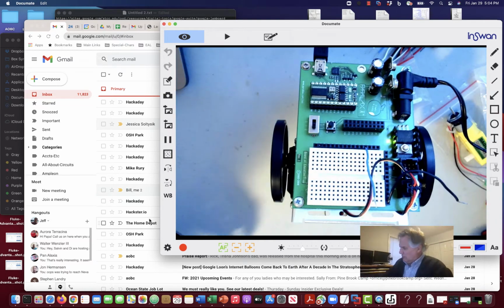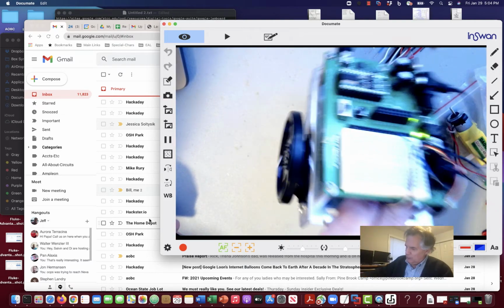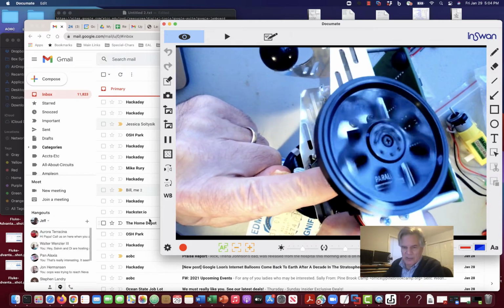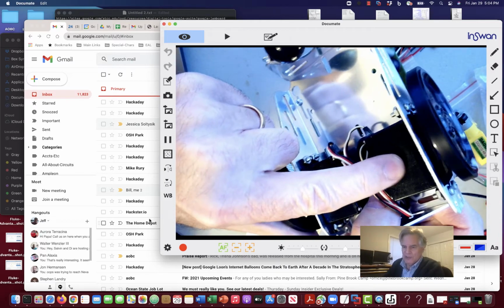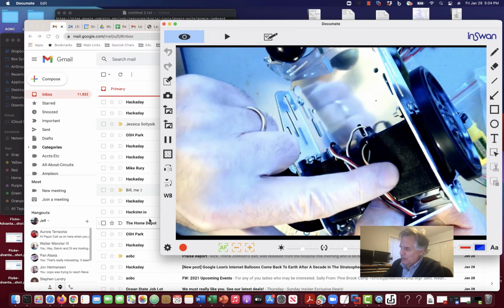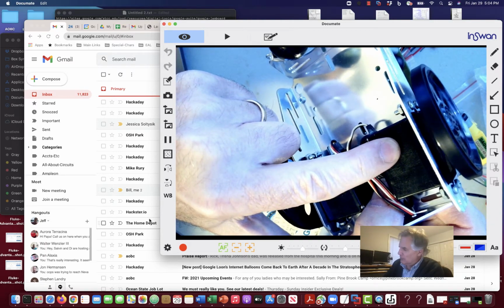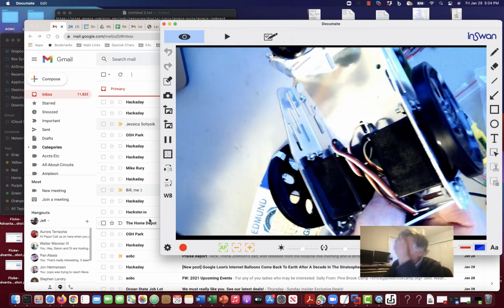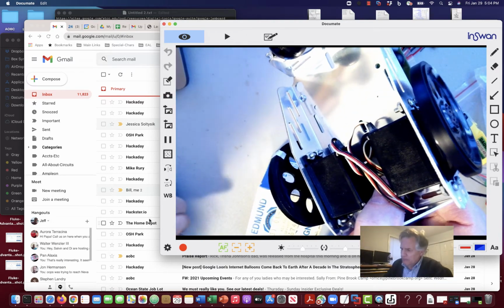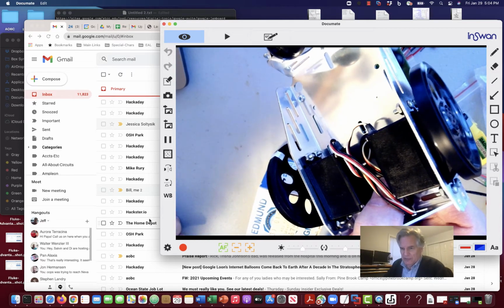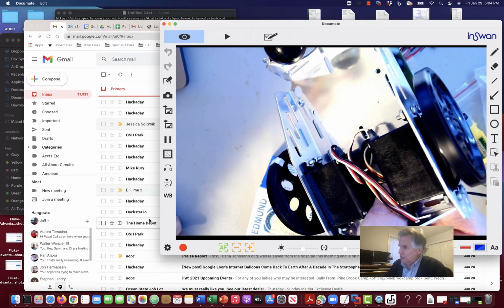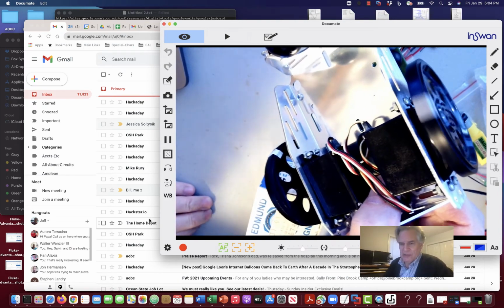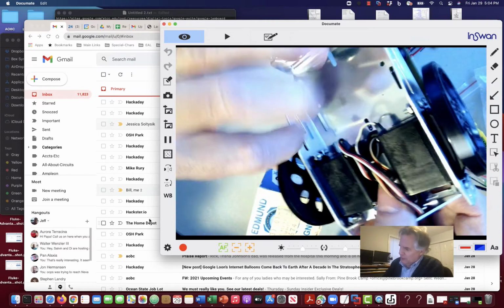Take this off of here. I think you're familiar from building your Bobot that there's motors in here. There's some kind of mechanism in here that watches the motor turning and matches it to the average value of that signal that you're putting out. Okay. Fatter pulses mean going faster in one direction. Narrower pulses, when you get narrower than 750 or 1.5 milliseconds, then you're going the other direction.